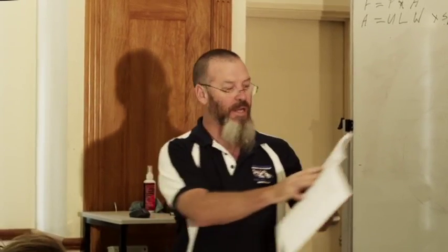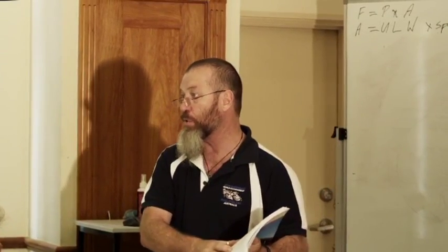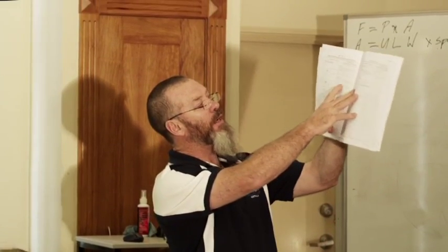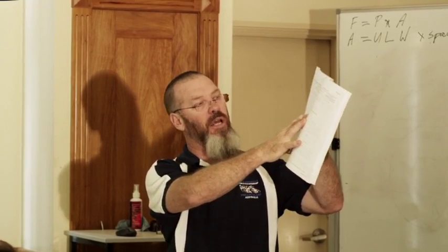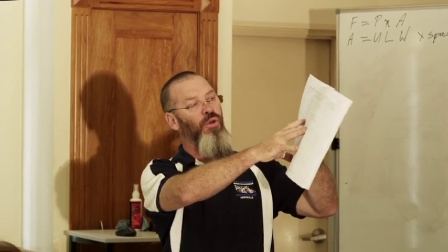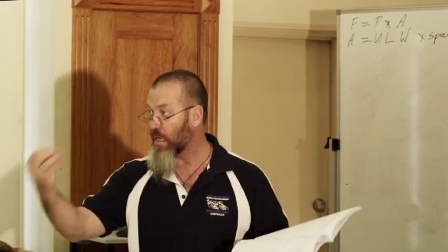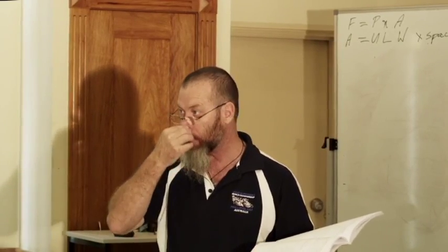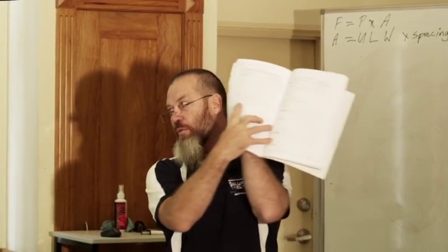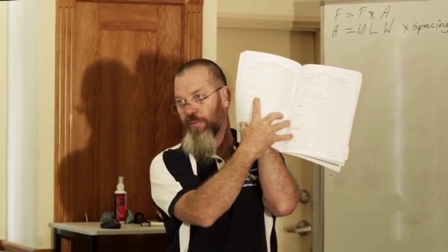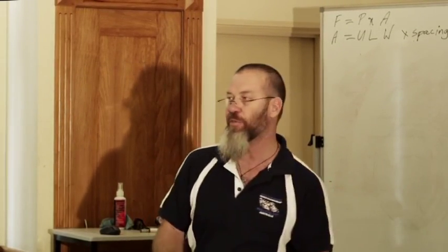So you start at JD5, and we're after that 0.29 of a kilonewton that we've calculated. So I start there and I go, one plain shank nail won't do it, 0.21. So you go to the next one, and you'll see two 3.05 nails will give you a resistance of 0.42. So that's equal to or greater than that 0.29, isn't it? But look at this little note over in the corner. See the note there under my finger? What it says is 2 screws shall be used only with 75mm wide battens.